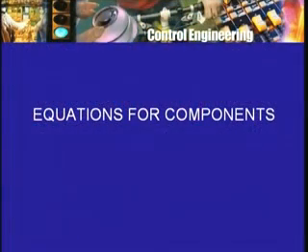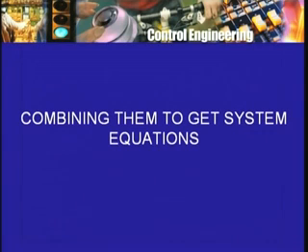So the system is built out of components, and one may start by writing equations for the components first, and then looking at the equations together or combining them to get the equations for the system. So do it for the RLC series circuit. Start at the very basic level, start with each one of the components, resistor, inductor, capacitor, voltage source. Write down the equations that describe only the component, each component separately. Write down an equation that describes only the resistor, an equation that describes the behavior of the resistor under normal conditions.